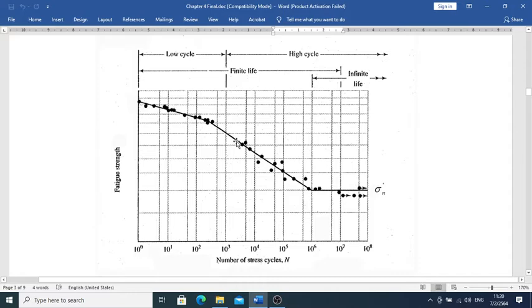It's going to bend down all the way up to a certain steady line there. You're going to have the sigma n, that's what we're waiting for. The sigma n is the thing that becomes a constant, steady value. That's what we're going to use as the fatigue limit or endurance limit. That's what we want to have here. This kind of graph comes from the experiment here, and that's what I would like you guys to pay attention to.